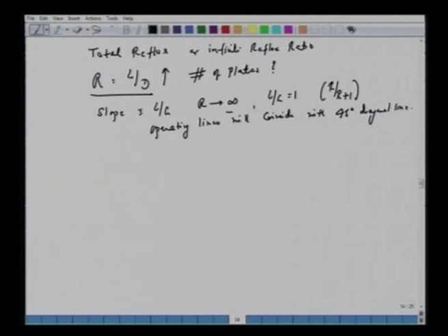Okay, so physically, all we are trying to say is that when you have the distillation column and keep increasing the reflux ratio until we have infinite reflux ratio, there is no top product withdrawn. In that case, even at the bottom, the entire vapor has to be sent back to the distillation column through the reboiler. So essentially the feed has to be switched off and the entire liquid circulates within the distillation column. It's a hypothetical case, but these conditions will give us the minimum number of plates.